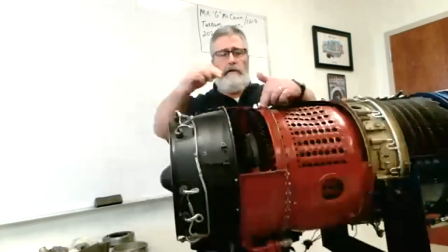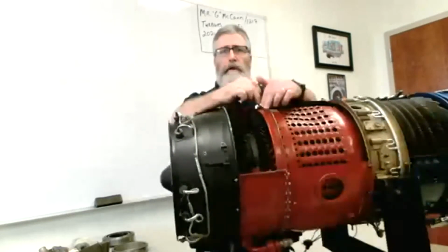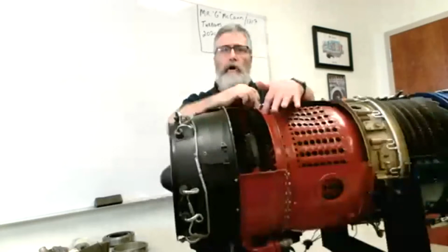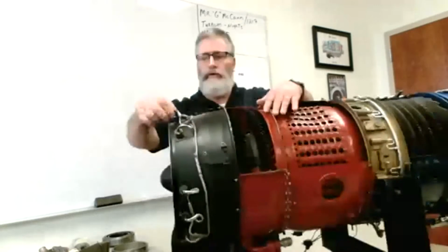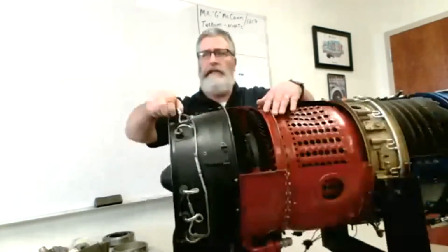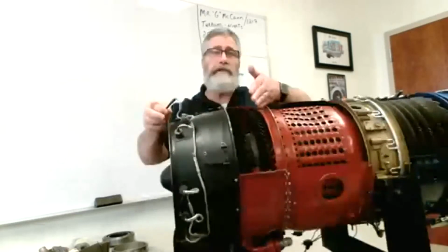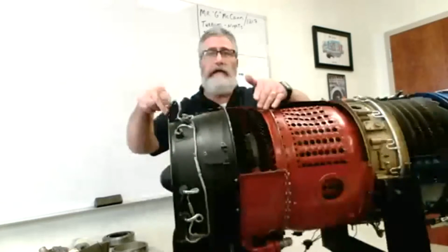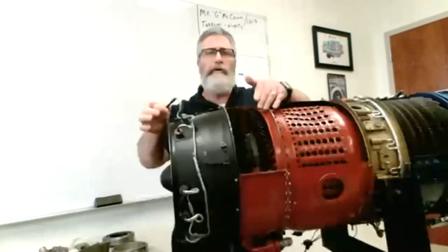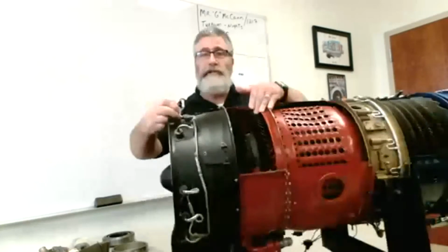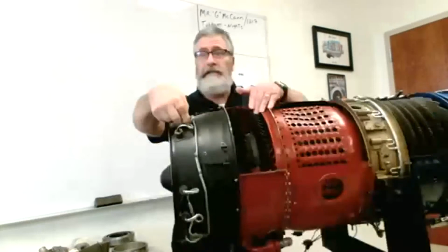So, therefore, the probes would be under a much more hostile environment. They would be much more expensive. They would probably need to be replaced more often. What a lot of manufacturers do is they use an EGT system, which basically, if this is running at 1,700 degrees Celsius, by the time we get to the exhaust, this might be down around 600 or 650 degrees Celsius. So that's just kind of a way to monitor temperature without exposing these probes to a very, very high temperature.